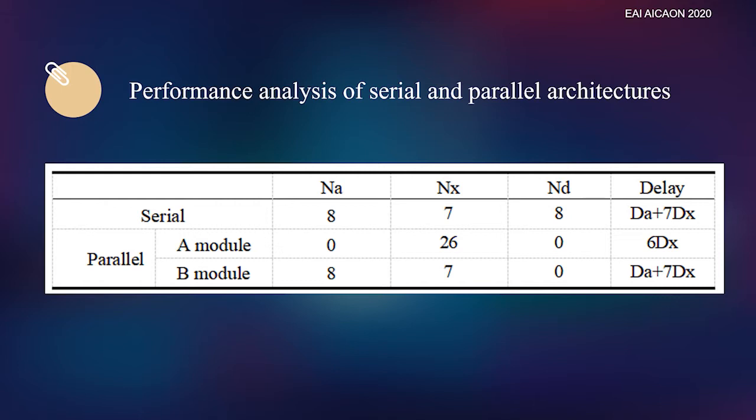This is because the CCSDS Reed-Solomon code decoding scheme, the common Berlekamp-Massey algorithm, includes an algorithm using multiple multipliers. These multipliers share the same conversion and only need one conversion. We can see the XOR gate resources occupied by parallel multipliers are more than 4 times that of the serial multipliers.